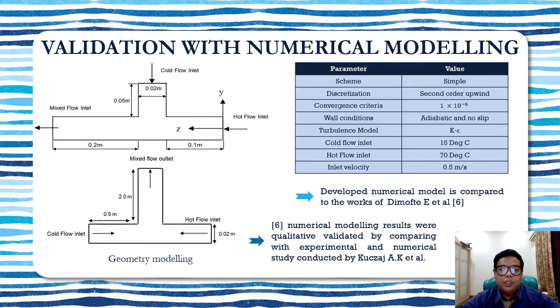The result obtained in their studies was computed using the commercial package of ANSYS Fluent and utilized the turbulence model of realizable K-epsilon. The method of solution for the pressure and velocity coupling is SIMPLE, with second-order bounded differencing scheme to be used as the diffusive and convective parts of the equation discretization for the model.